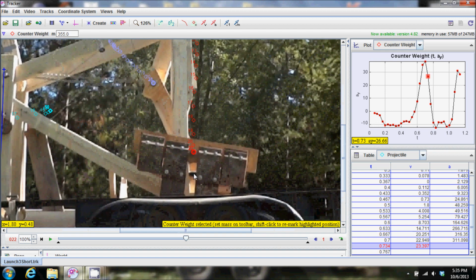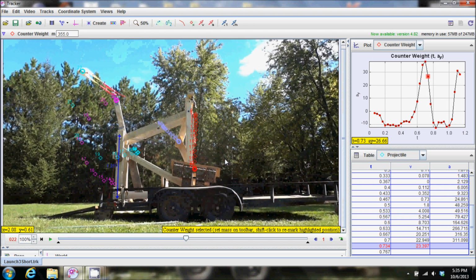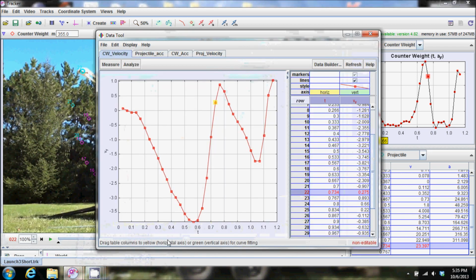This here's rubber bumper with wood underneath. If I move that up 4 inches, then that would probably make me 10% more efficient, simply because this is where my stall is happening and my projectile is releasing, and I wouldn't count this here. If I look at the peak velocity of my counterweight, the peak velocity is right here. We're at 3.8 meters per second.